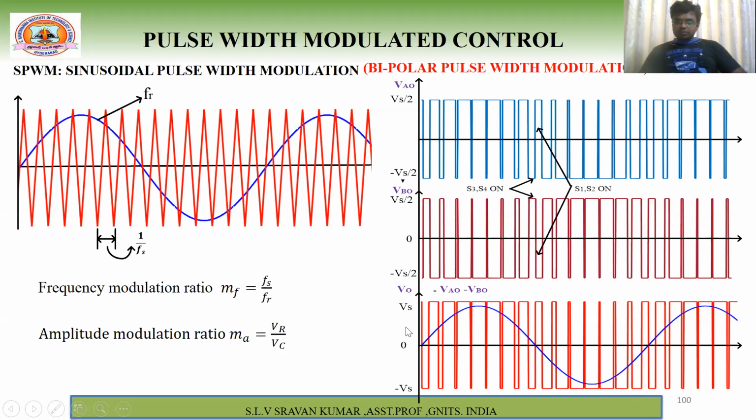So that means your fundamental waveform slowly started here. Whenever the pulse width is increasing, your output voltage is also increasing. Simple duty cycle. In the duty cycle concept, if the duty cycle increases, your output voltage also increases, like this. So duty cycle means the on time. See, the pulse on time is increased here, so that's why slowly it is increasing here.